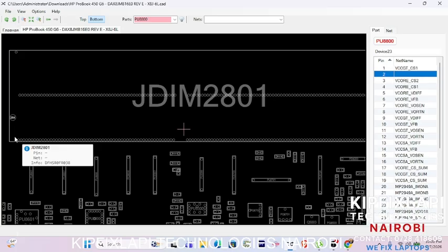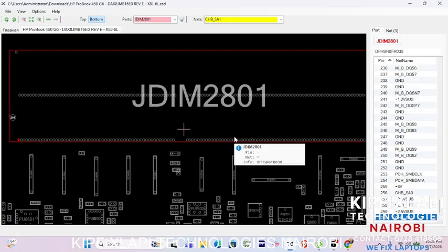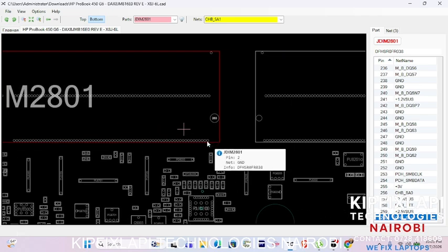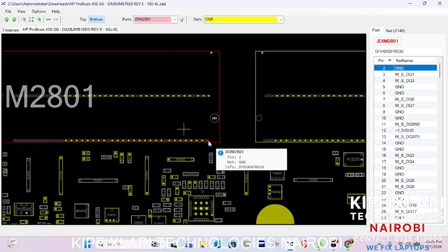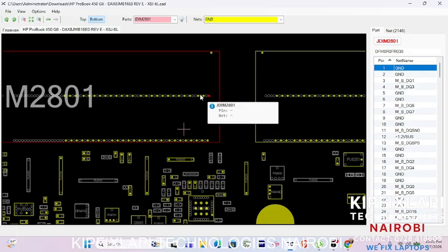As you can see, this RAM slot contains some pins all the way from this pin. So this is 260. I believe the pin number 1 should be at this side. Yes, this is pin number 1, and that is not even pin number 1, that is pin number 2. Here's the pin number 1. I believe the pins for this connector are alternating, because we have two lines in the connector. Pin number 1 is the ground.